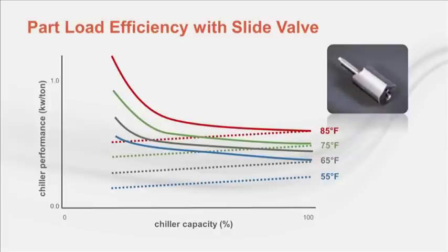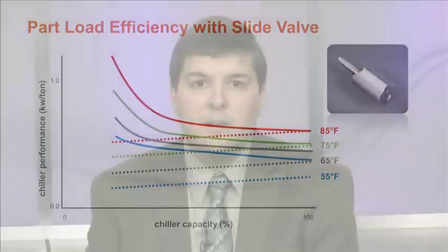Similar to centrifugal chillers, at lower capacities, screw chiller efficiency with slide valve unloading tends to drift away from the ideal target performance. Now that variable speed drive costs continue to come down, it has become more common to see them on the likes of rotary chillers. Some rotary screw compressor manufacturers apply variable speed drives in conjunction with a slide valve, port, or added mechanical unloading capability. Other designs apply the variable speed as the only means of unloading.